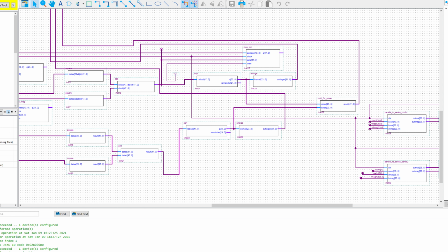So at this point, they are still 24-bit signals. Okay, they actually get doubled in size as you square the signal, but then they get halved in size again when we take the square root. And what I've done here is I've just made those signals a bit larger. It's not adding any new information. It's just turning them from 24-bit signals to 32-bit signals.